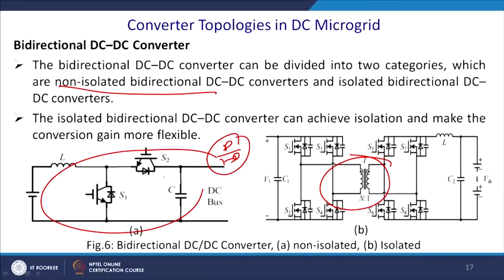and you know that actually the transfer function will be given by d by 1 minus d here, and here you can also play with the turns ratio, because once you require to buck a high voltage, the current sometimes becomes discontinuous, and in that case the control system loses its predominance.